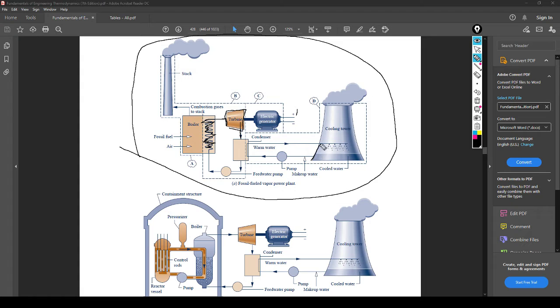Essentially, what's happening in here is basically just steam. It's water vapor, so it's not actually anything bad. It just looks like that from the outside. But essentially, this is a cooling tower. And if you do Thermo 500, you analyze this stuff, which is really cool. You actually have to do a question about cooling towers, like how much water is falling down. It's a psychrometrics problem in a lot of ways. Psychrometrics being the study of humidity.